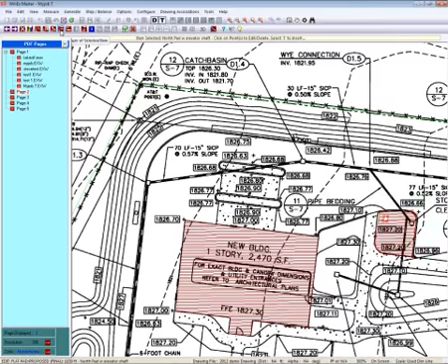In our WinEx Master software, you can work in 5 intermediate phases or layers, so that if in layer 1 you're coming in, you're going to do a little demo work and you need the numbers and the maps just for that phase. Phase 2, you're coming in, you're going to maybe lay down a pad or a parking lot. Phase 3, you're going to do a little bit more cut, put in a retention pond.